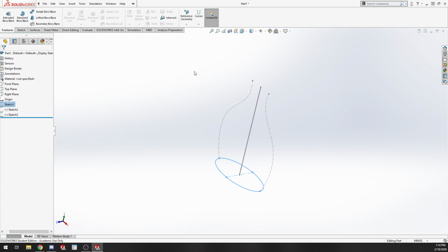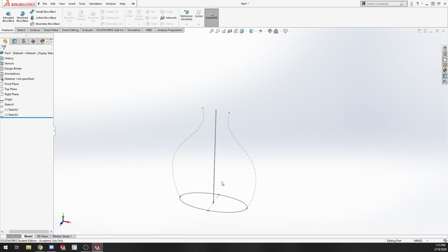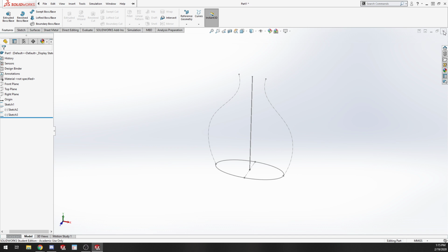Yeah, I'm still stumped with sweeps, so we'll go through this. Maybe I'll have to figure it out 100% and then make a little short video on it. But if you saw in there, if you're starting with one profile and a path, you want to use the sweep. If you're starting with intermediate profiles, like if I were to make a bunch of cross sections and a bunch of ellipses every 10 millimeters or so, I could use a loft or a boundary for those. So let's just move right into assemblies, because that's really what we're here to talk about today.